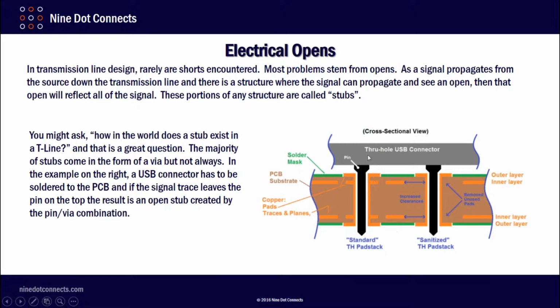So in this situation, my signal is supposed to come in the USB connector. It comes through this portion of the metal conductor, and it comes out this annular ring and gets on a trace and runs out the trace. We end up having the rest of this piece of metal acting like a little miniature antenna, so to speak. It's a series inductor. And during this portion of the circuit, we also have capacitance that's distributed along here. Keep in mind, a transmission line, by definition, is distributed inductance and distributed capacitance. That's what you have on a smaller scale, a mini transmission line for that section.